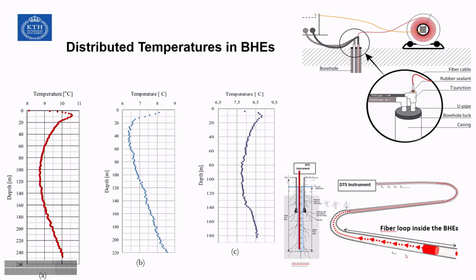In the middle, on the other hand, you have a borehole outside the city where you see the geothermal gradient pretty much from the beginning. And for this type of installation, the measurement is normally done in connection with a thermal conductivity test. So besides connecting the rig, you put the cable in one of the 2 pipes, normally the downward fluid, which is a bit warmer, with a T-junction. And then you measure the undisturbed profile and then the rest of the measurement.